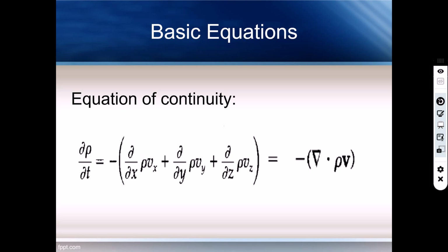If it's an incompressible fluid, you get this thing equal to 0. It means it moves with the fluid, but the density does not change. In the previous cases, you don't move with the fluid. You measure at this point, and so the density can change because you may encounter other fluid. But here, you move with the fluid. If it's an incompressible fluid, the density cannot change.